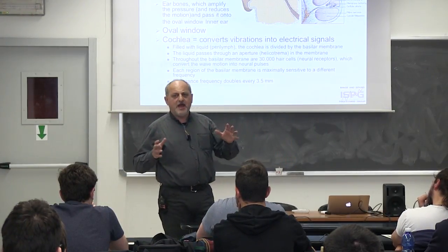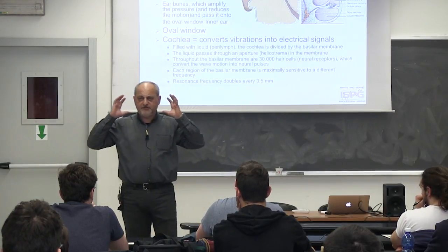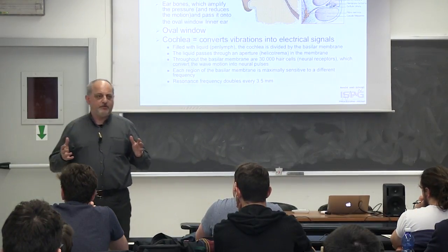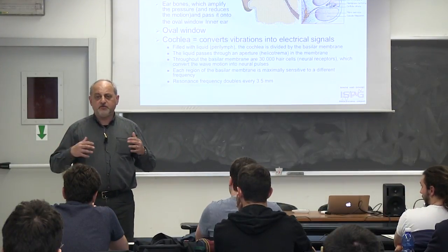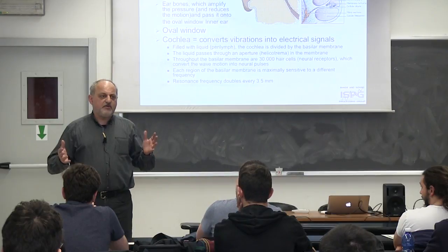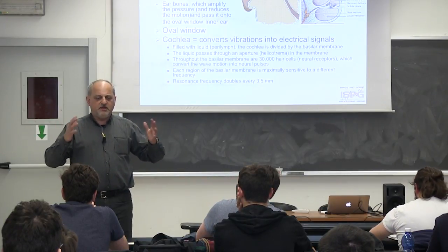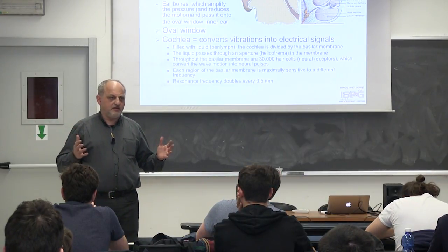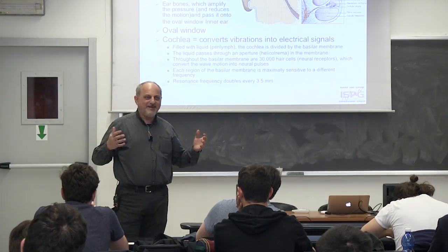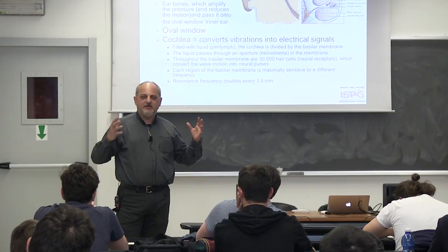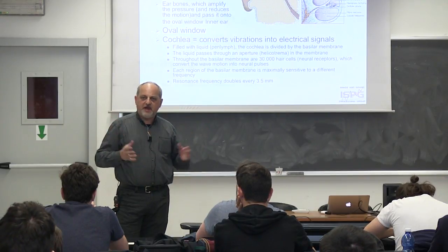There are many other things that happen, but for example, the filtering per se is actually a bandpass filter. So it takes away many of the low frequencies, many of the high frequencies, because most of the information in speech is actually in a range of about 5,000 or 6,000 hertz, starting from about 100 hertz. So you don't need big ears, fortunately, but you just need the size that is adequate for those frequencies.